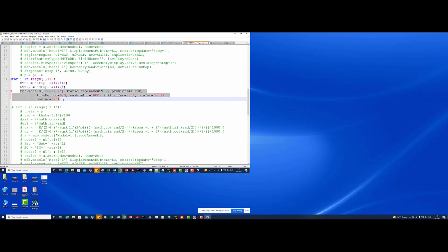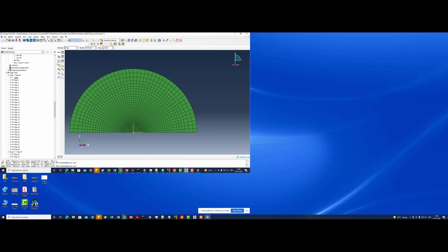so I just used the macro manager recording system of Abaqus, and a little bit of common sense here and there, and you can change the coding to suit whatever you want to do. This way you can code approximately everything you do in the graphical user interface, including partitioning, sketch making, meshing and everything. Each and everything of the software can be coded using Python. Okay, is it making any sense to you? Do you understand? Okay, all right.